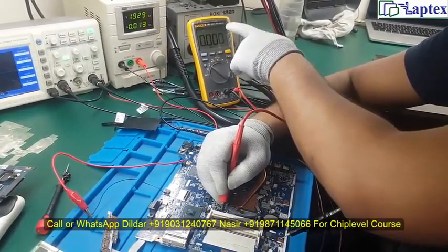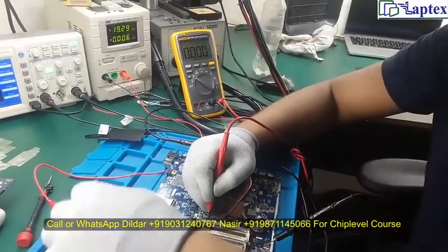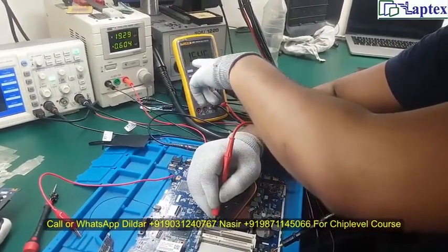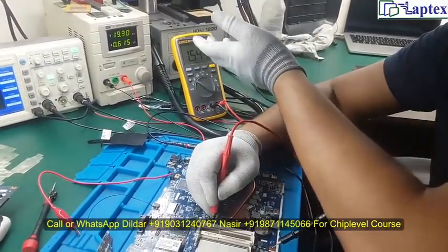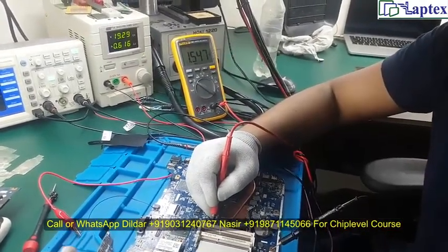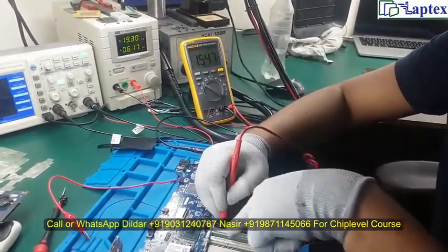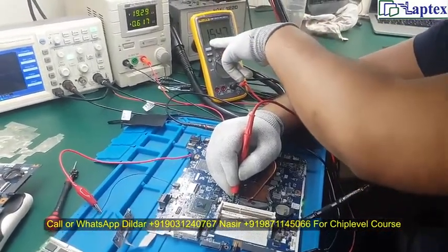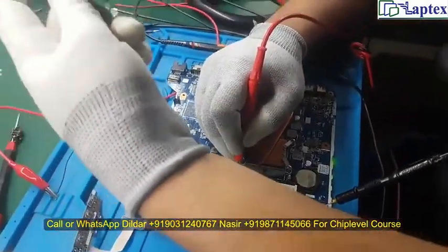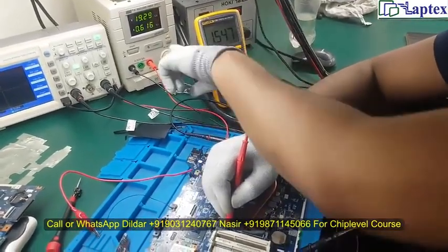As you know, the VDDQ voltage is generated in the motherboard after getting the SLP S3 voltage from the PCH. So let me turn it on. After turning on, all the processes have executed, and the RAM IC has produced 1.5 volt for the DDR3 RAM supply, and in the same place the DDR RAM reset is pulled up by 1.5 volt. I was getting the same voltage with the RAM in the slot, and also without RAM we are getting the same voltage. We cannot differentiate between both.